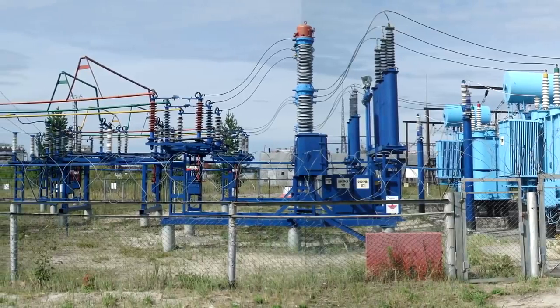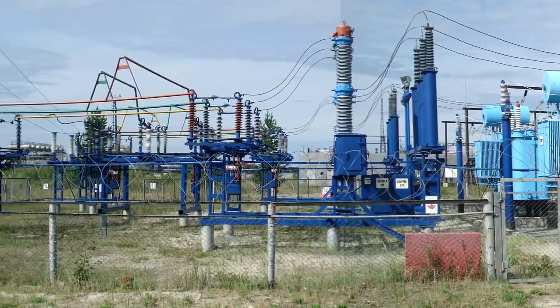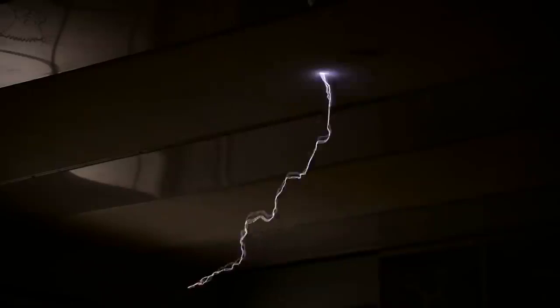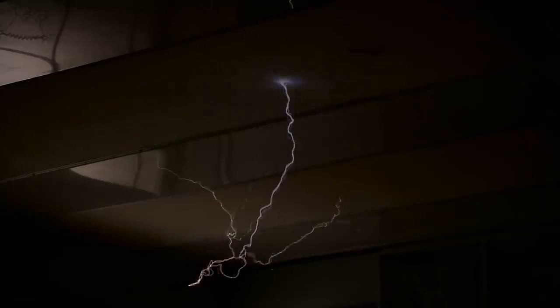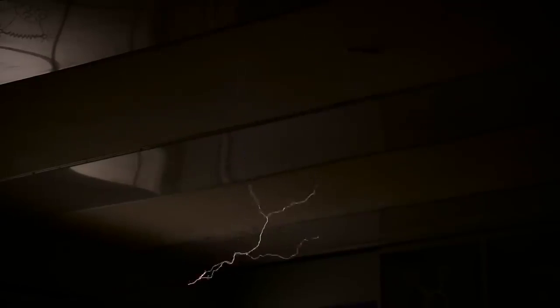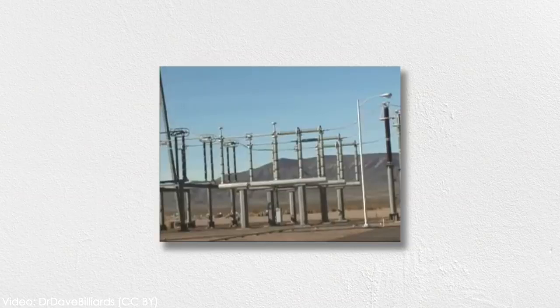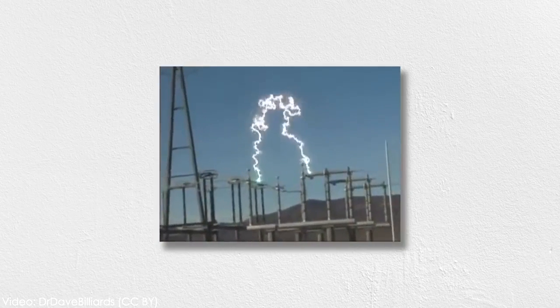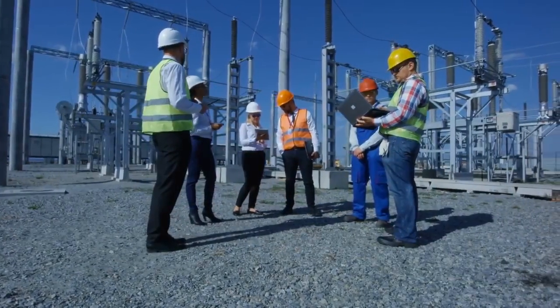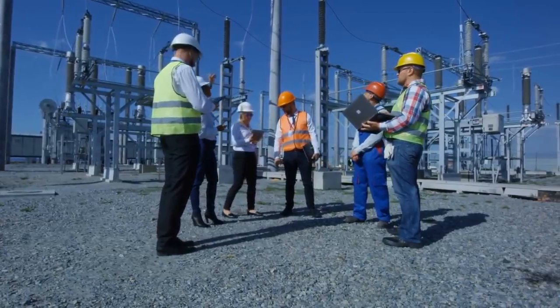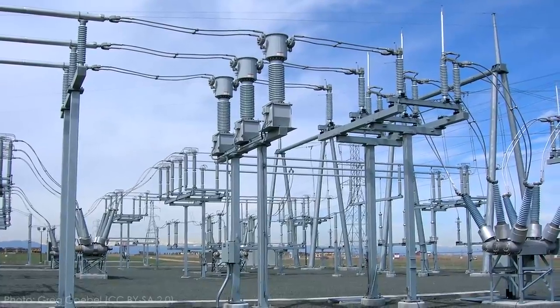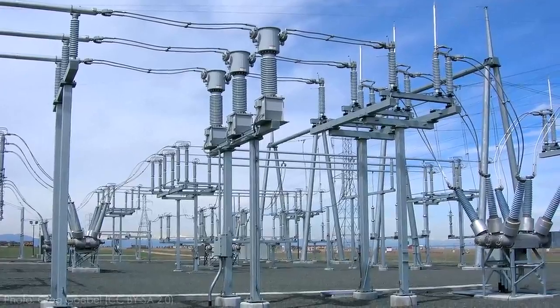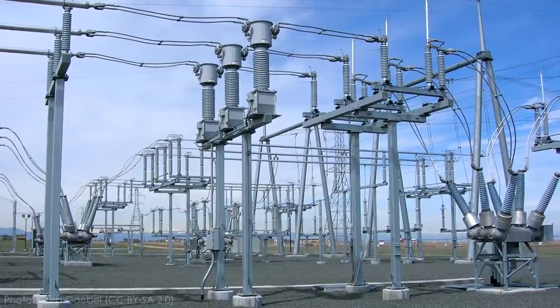This may seem obvious, but turning on and off high voltage lines isn't as simple as flipping a light switch. At high voltages, even air can act like a conductor, which means even if you create a break in the line, electricity can continue flowing in a phenomenon known as an arc. Not only does arcing defeat the purpose of the switch, it is incredibly dangerous and damaging to equipment. So switching in a substation is a carefully controlled procedure with specially designed equipment to handle high voltages. Disconnect switches are often just called switchgear, in addition to the equipment that serves another important role in a substation: